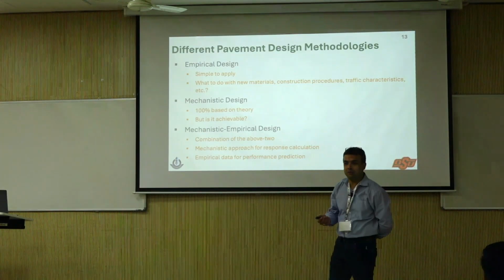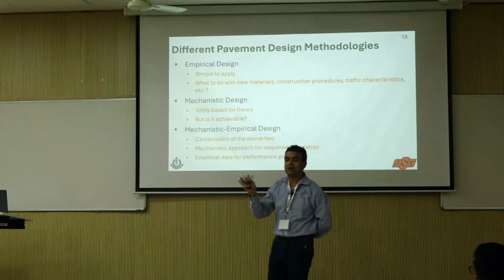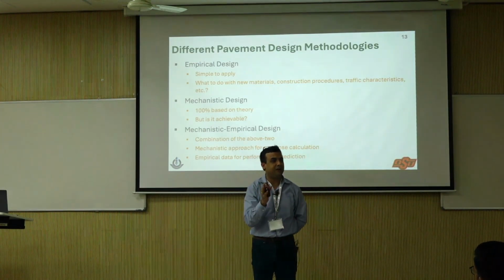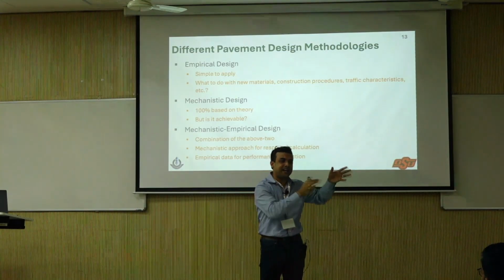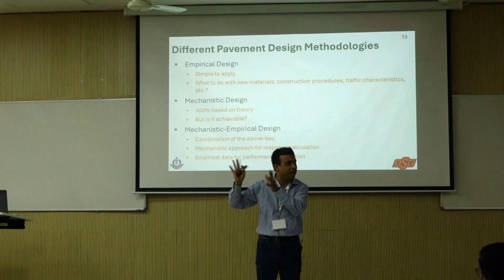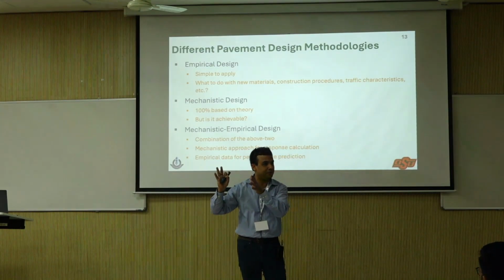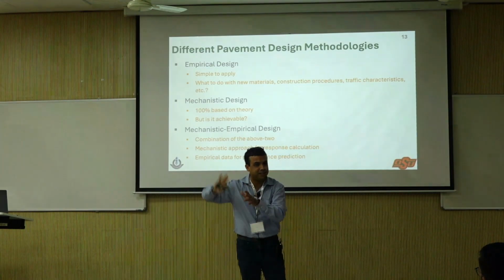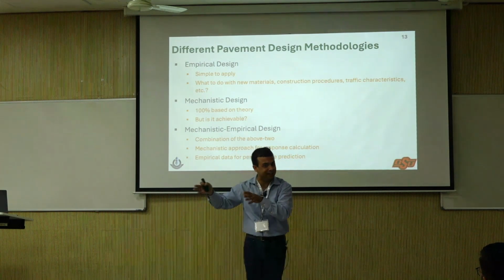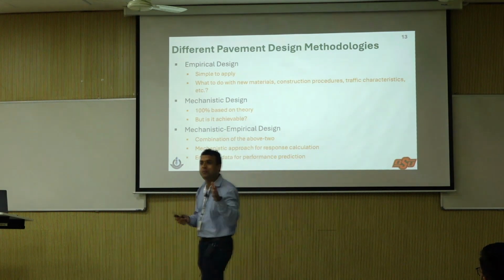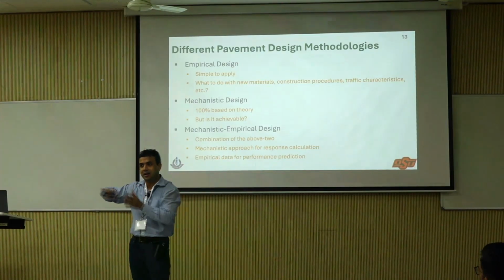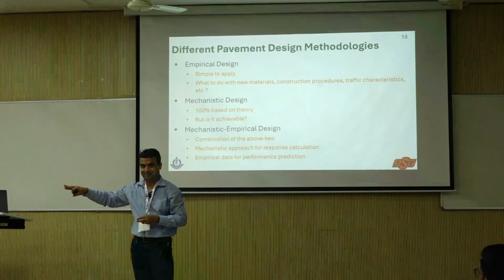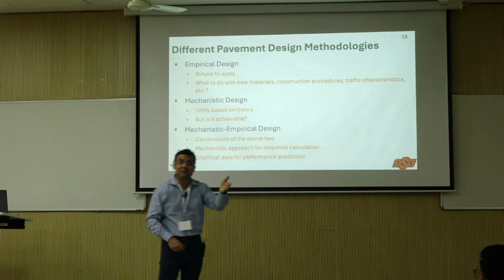Those of you who have worked on asphalt mix designs know there is something called the target mix design, and there is something called the job mix formula. I don't know what the term is in India, unfortunately, but the actual formula that goes in the plant is different from what you are constructing. So you build all your models for something, and the road is constructed with completely different material. That's the reason it's not possible.